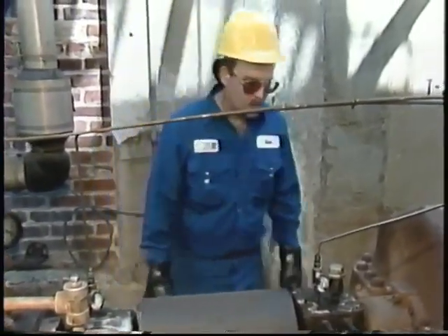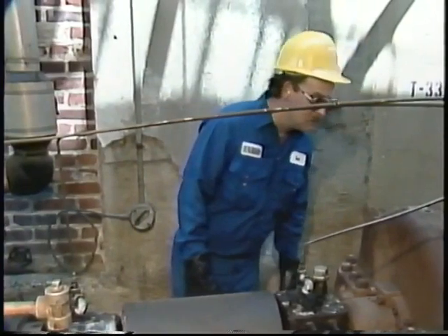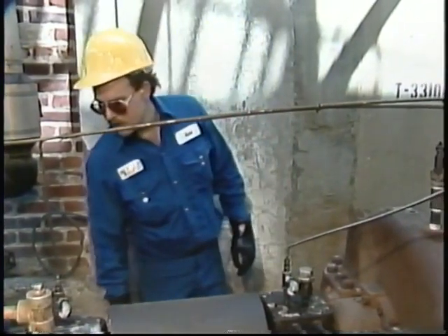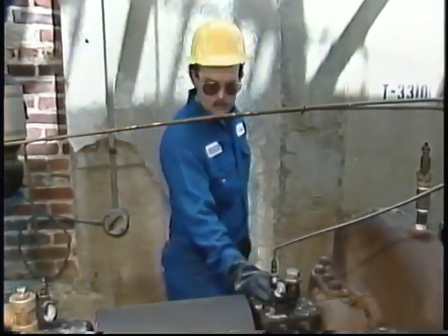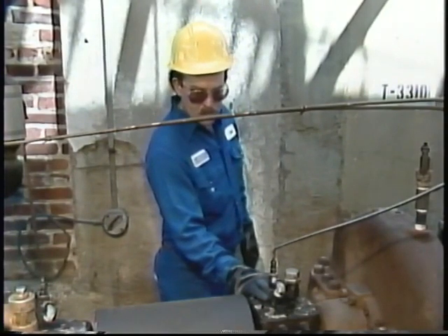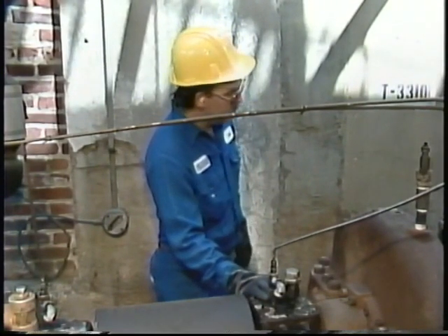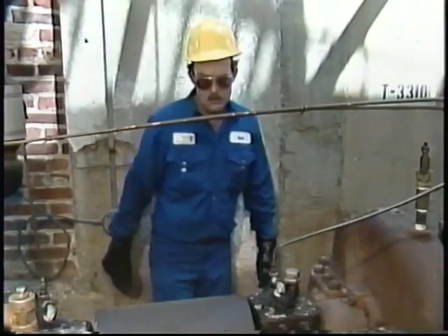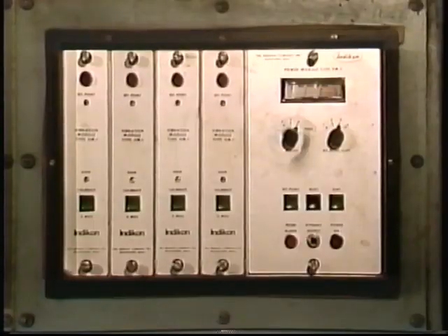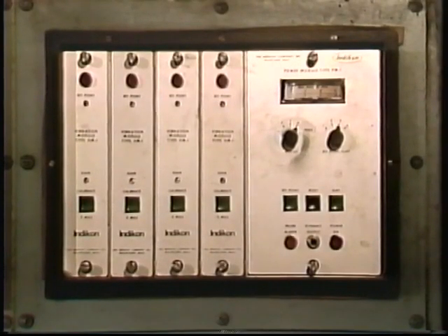Two ways to detect excessive vibration are by listening for unusual noise and by looking or feeling for abnormal vibration at the governor, bearing housings, turbine casing, and the coupling. Your facility may also have special vibration monitoring or analysis devices.